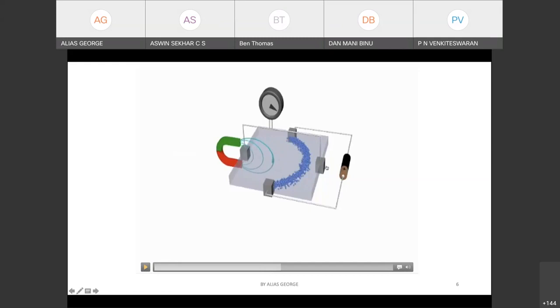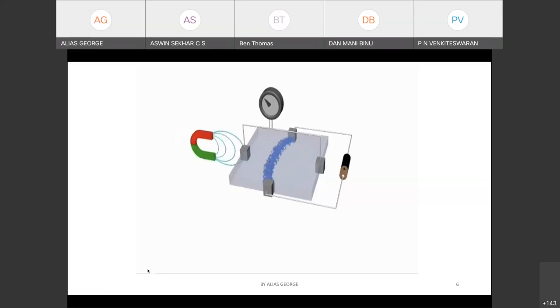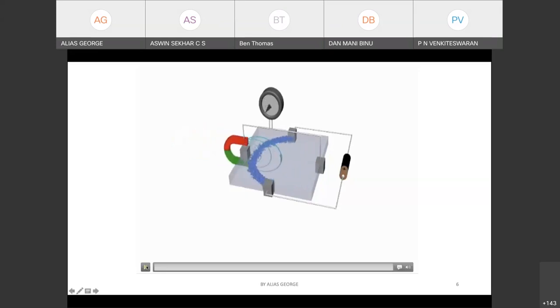We measured the bottom and top with a multimeter, and it shows some Hall voltage, a positive Hall voltage. You can reverse this direction, and the electrons will be pushed to the other side, and now the Hall voltage is negative. Is that clear? Everyone understood this?